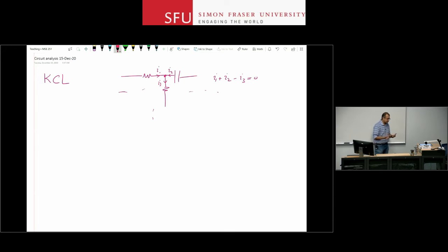And the answer is that, well, we all know that current is moving charges, right? So basically the number of charge carriers that you have per second gives you the value for the current. So if the sum of the currents that enter a node is larger than the sum of the currents that leave the node, then the number of charges coming in is larger than the number of charges leaving that node.